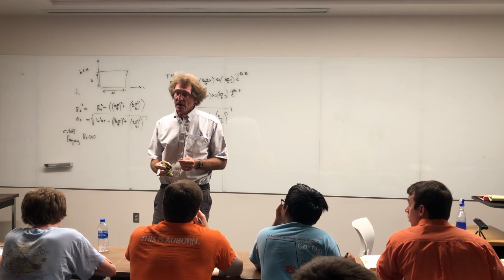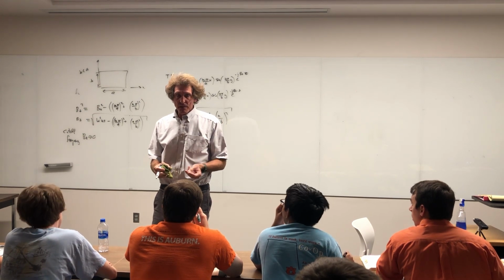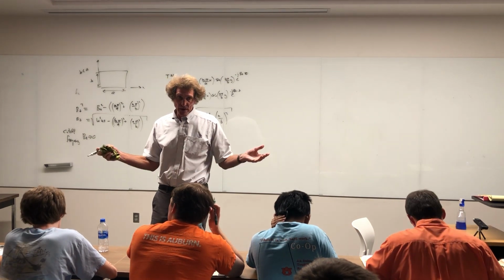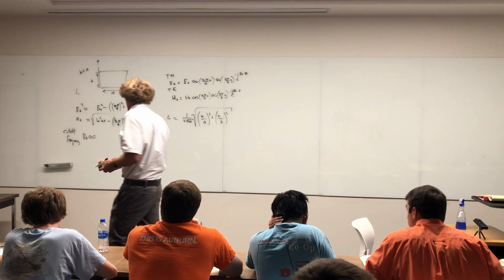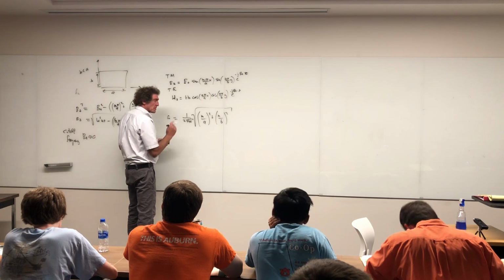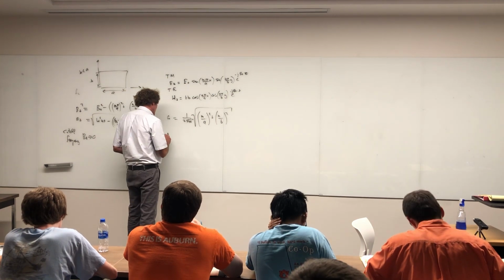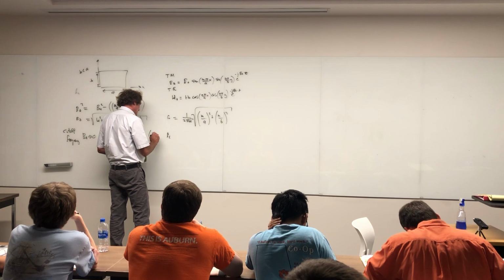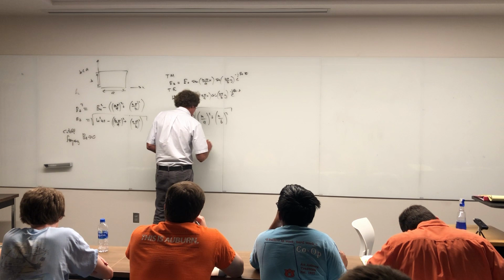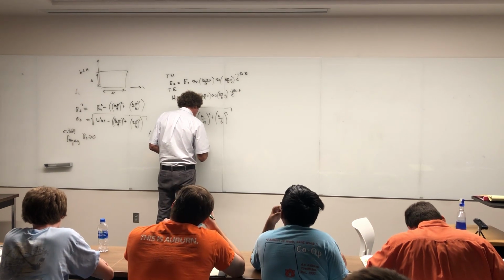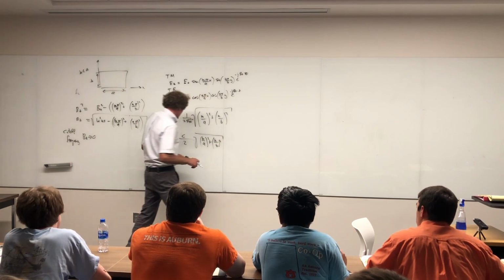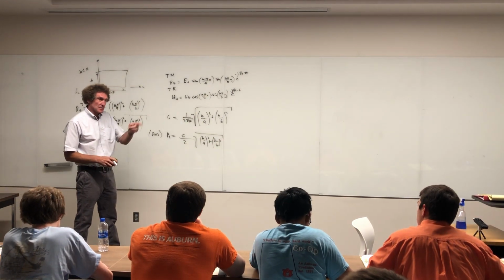C. In free space, it would be the speed of light, right? But it's really the velocity of propagation in an unbounded media, if it's not in a waveguide. Follow me if it's just mu and epsilon. So just remember, especially if it's filled with air, you can just put c here. All right? If it's air-filled, you can put fc equal to c over 2 times square root of m over a squared plus n over b squared. That'll work for an air-filled guide, and I think this one's air-filled.